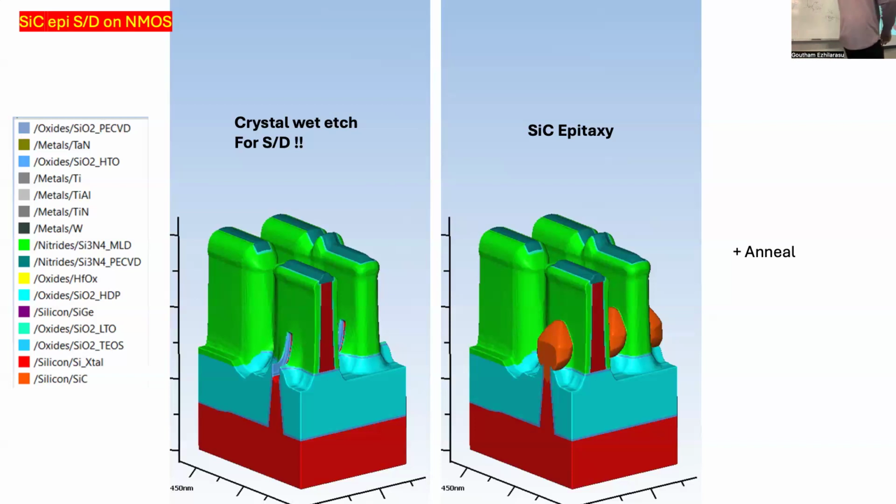We were talking about a spacer like 10 minutes ago. Where is that spacer? This is the spacer. So before we do any of this strain engineering stuff, deposit a spacer. Remember, to create the lightly doped drain region. Protecting that lightly doped region, that's why this is there. This is the sidewall. This sidewall spacer is here, and that's why this protects you from opening the silicon where the lightly doped region is. So the lightly doped region is sitting below the sidewall spacer, right? And then you open up this region and then you grow the silicon carbide.